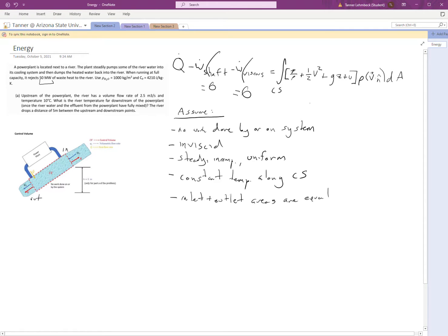And really the math is no different than what we've been doing with control volume analysis, right? So if we assume constant pressure across the surface, constant velocity across the surface, and we did that, we said it's uniform. Constant height at the surface, which is also a pretty reasonable assumption to make. And constant internal energy across the control surface. So it falls in line with this constant temperature assumption. We're basically assuming that the energy of the particles passing through the control surface at each point is the same, so we have a constant energy flux across that control surface.